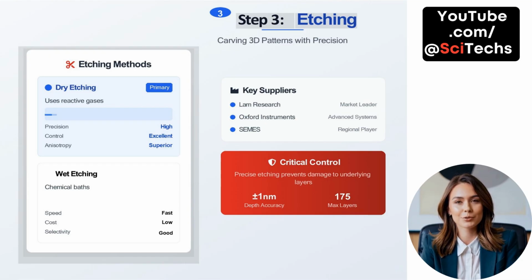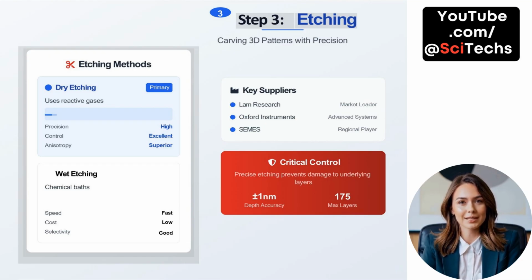Dry etching uses reactive gases in a plasma state to achieve high precision, excellent control, and superior anisotropy, meaning the etching is highly directional. It is the primary method used in advanced manufacturing today. In contrast, wet etching relies on chemical baths. It is faster and more cost-effective, with good selectivity, but offers less control and precision than dry etching.